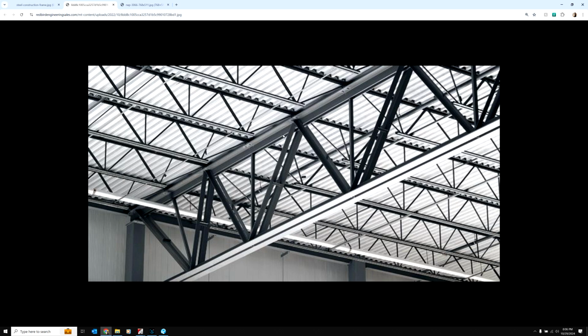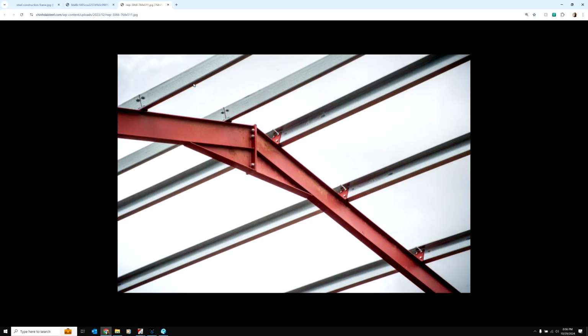So this is a K on a drawing, your I-beams are a W, and really the last thing you run into every now and then, this would be like a pole barn kind of structure, just warehouse spaces. This is called a Z Purlin, and it is because it is shaped like the letter Z. Very thin gauge steel, supported by heavier steel. This is really little more than strong enough to hold your roof up. You've got to be very careful about how much weight you put on a hanger on the edge of one of these thin gauge Z Purlins.